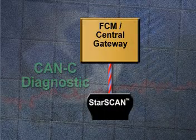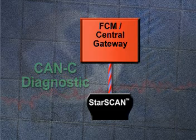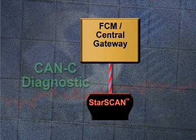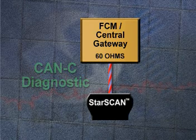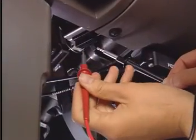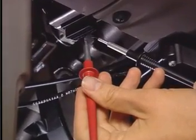Actually, in this case, you can refer to the items on the bus as nodes, since in addition to the central gateway, the StarScan is a participant on CAN-C Diagnostic when it's connected to a vehicle. Another difference is the termination resistance, which is around 60 ohms at the central gateway. Just as with CAN-C, the resistance is present with the key off, and you can check it with an ohmmeter.